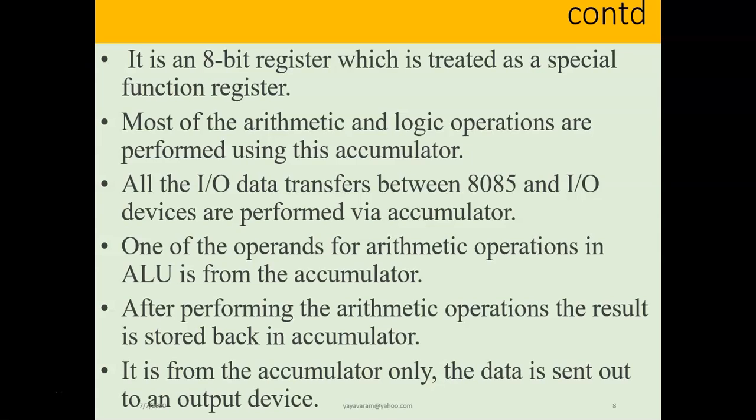If I want to use a shift instruction, this will work only on the accumulator. Then someone may get a doubt: how do we perform shift on data which is in other registers? We have no other option except moving that data first into the accumulator, then performing either shift, I/O operation, rotate operation, or complementing operation, anything.